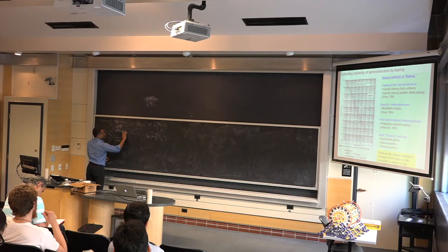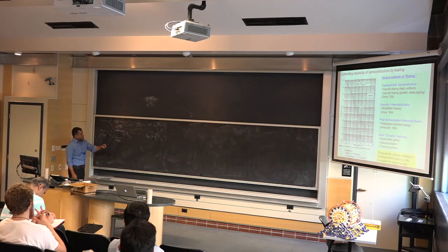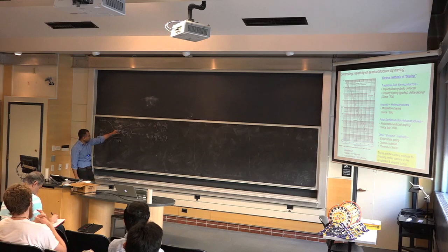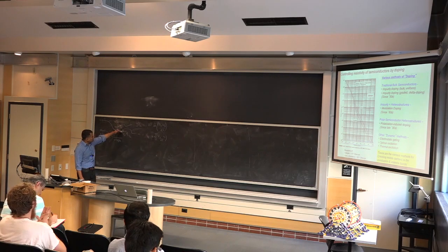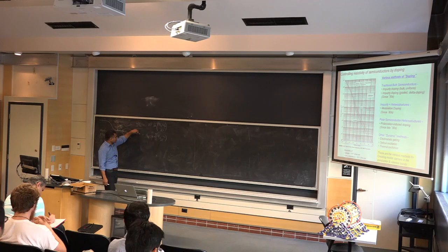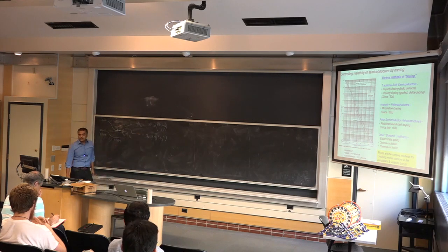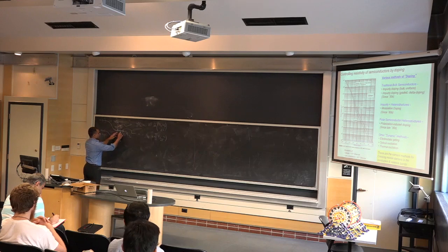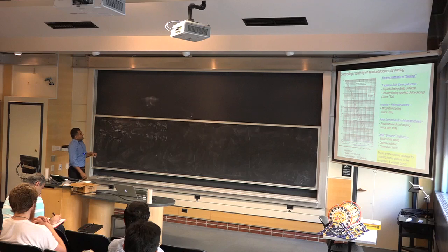That's the electron density. Fermi level is this line, and that is the band edge. So you can see here, for example, the way it's drawn, EF minus EC is negative, right? As a result, the electron density in the conduction band is less than the conduction band density. So that's pretty clear from here. If you dope it very heavily and you push the Fermi level into the band, it can be a little larger. So that's the number of electrons in the conduction band.